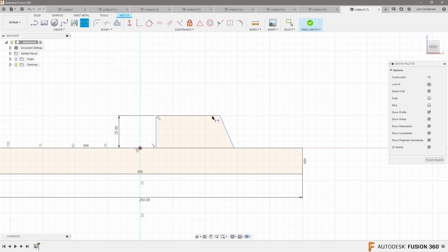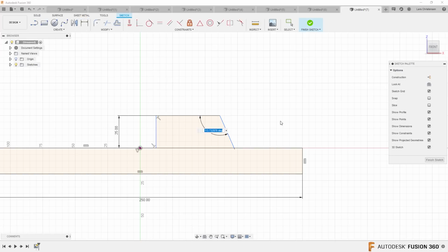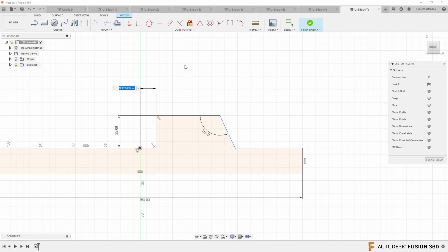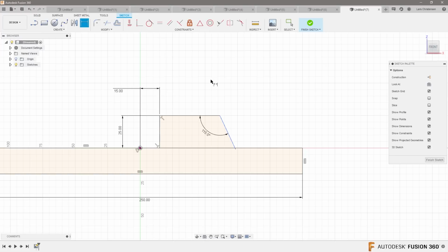Let's create an angle from here to here. That's going to be where it is when it's closed, right? It's going to fit in there. And let's just do 15. And then we probably need some other dimension here, 50. So that's our side view in. Bottom, the core side sitting, the core plate with the slider on it here.